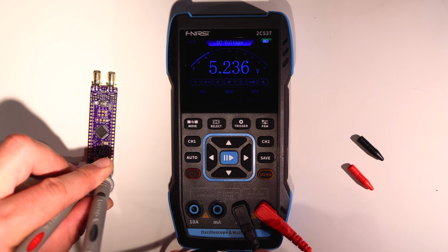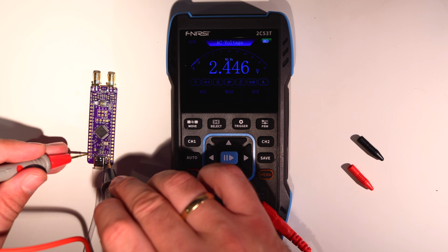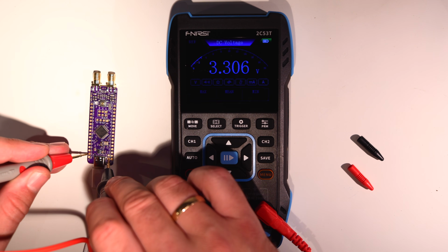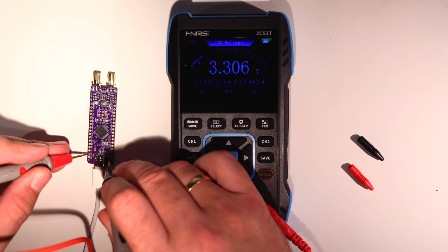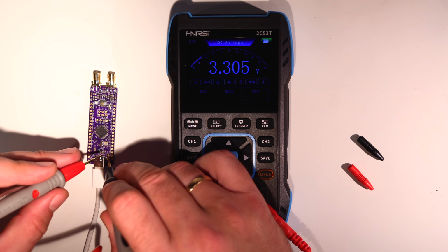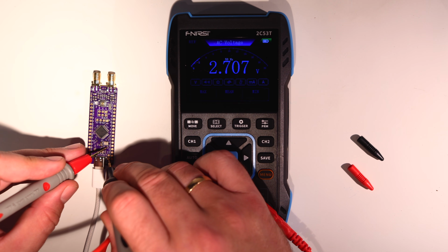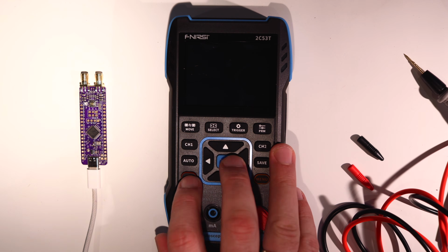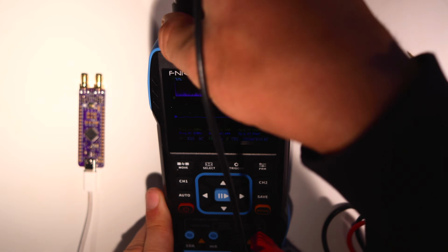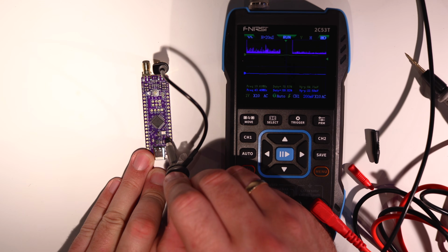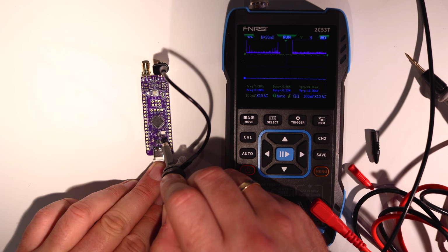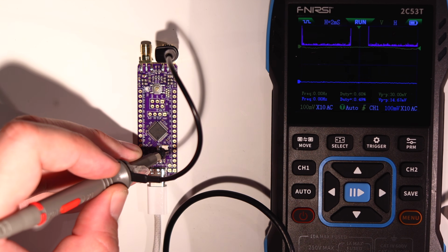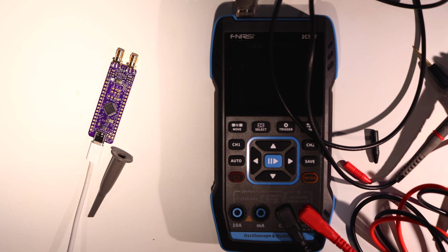Looks like we have 5.2 volts coming in through USB-C, and the onboard LDO is happily supplying 3.3 volts to the chip. Yay! I'm also a little bit curious if the oscillator is running from the factory, but probably not. Nope, nothing making 8 MHz and nothing making the slow crystal tick either.